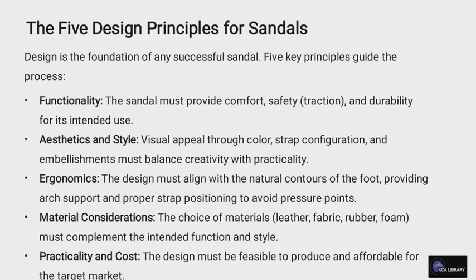The design must align with the natural contours of the foot, providing arch support and proper strap positioning to avoid pressure points. Another is material consideration, which is the choice of material in terms of leather, fabrics, rubber, and foam, which must complement the intended function and style. The last is practicality and cost, which talks about the design being feasible to produce and affordable for the target market.